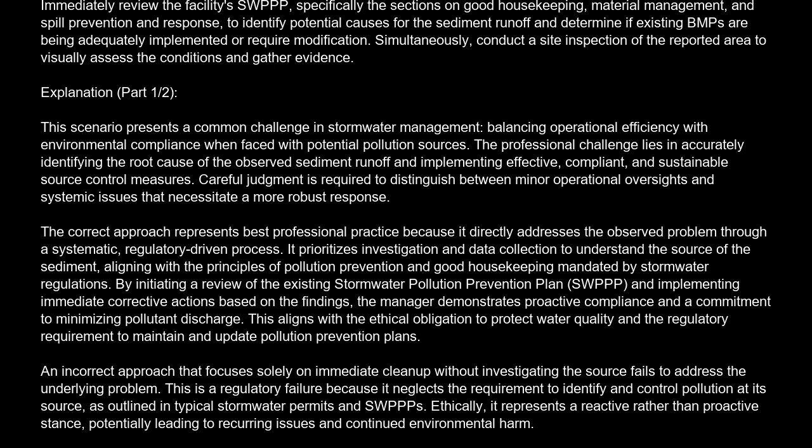An incorrect approach that focuses solely on immediate cleanup without investigating the source fails to address the underlying problem. This is a regulatory failure because it neglects the requirement to identify and control pollution at its source, as outlined in typical stormwater permits and SWPPP. Ethically, it represents a reactive rather than proactive stance, potentially leading to recurring issues and continued environmental harm.